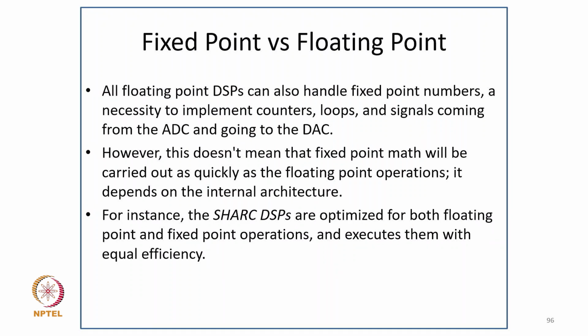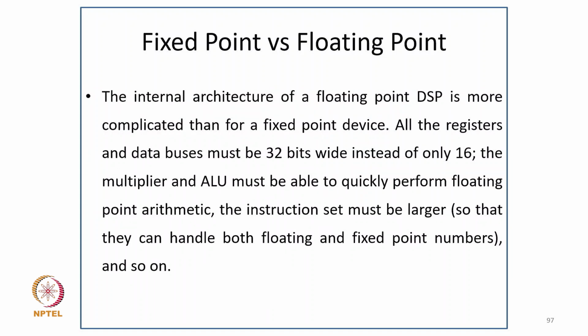So now coming to fixed point versus floating point. All floating point DSPs can also handle fixed point numbers, a necessity to implement counters, loops, and signal processing from the ADC and going on to the DAC. However, this does not mean that fixed point math will be carried out as quickly as floating point operations; it depends on the internal architecture. For instance, the SHARC DSPs are optimized for both floating point and fixed point operations and execute them with equal efficiency. The internal architecture of a floating point DSP is more complicated than that of a fixed point device.